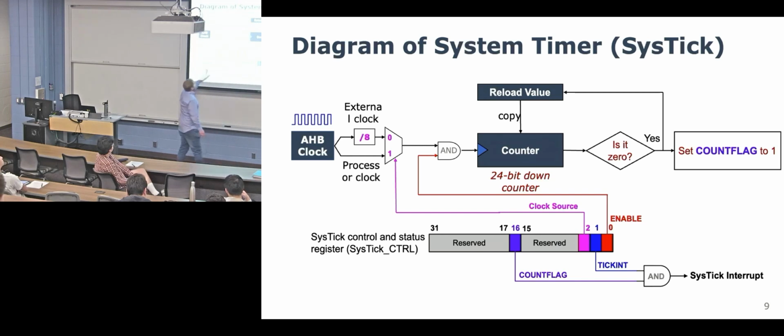Likewise, you can select 1 of 2 clock sources. There's a clock divide-by module that you can set up somewhere else. It's divide by 2, 4, or 8. So it's not a prescaler, it's a clock divider. You get your AHB clock coming in, and then you get to control which source it is. And so if you select a source, and then you just AND it into this AND gate, which enables this clock or not.